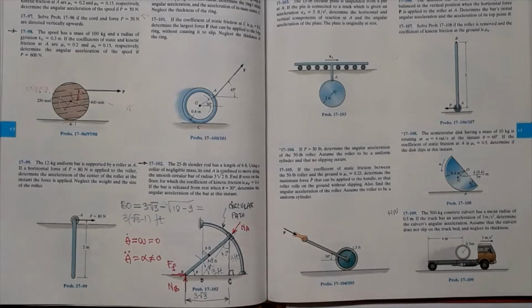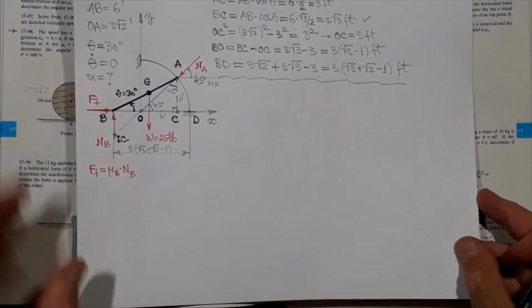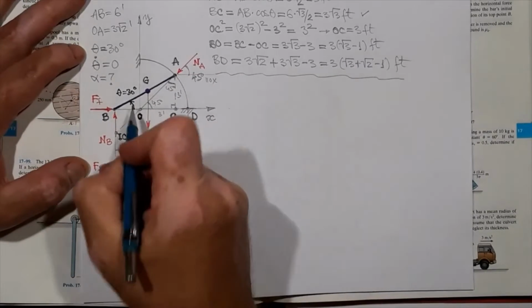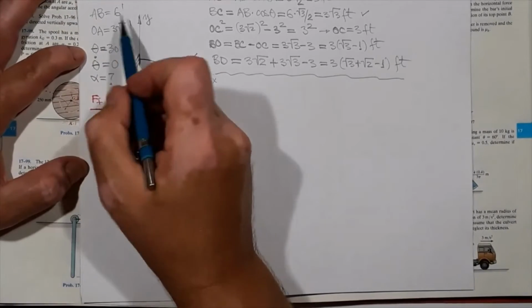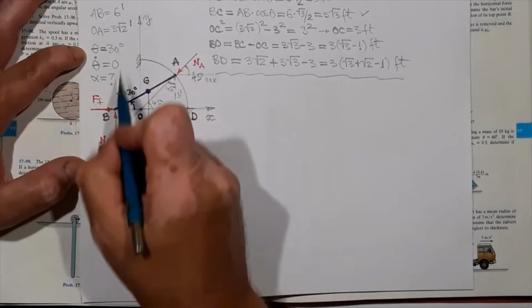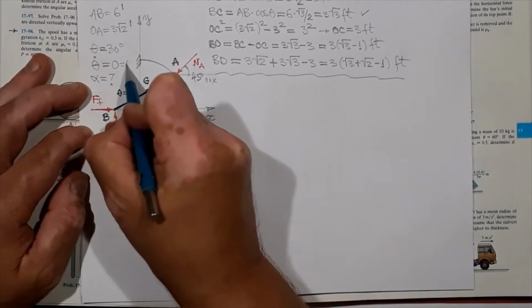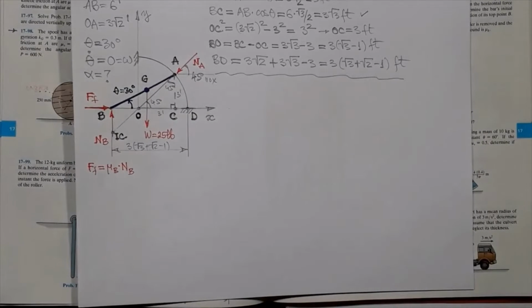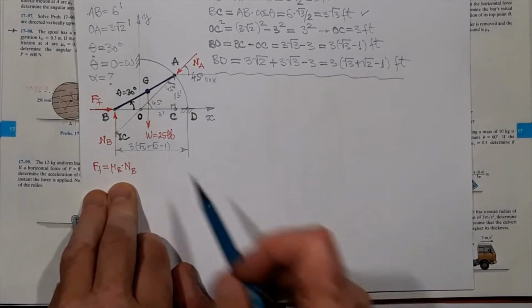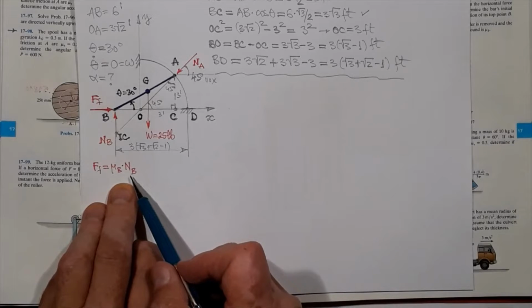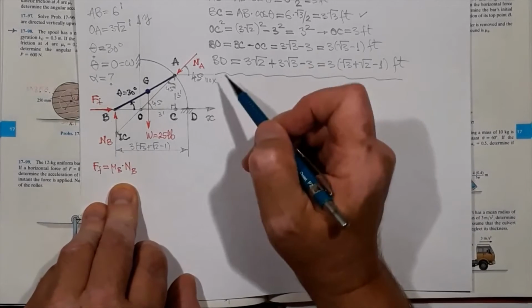of the bar. Okay, so I drew the figure here, trying to have it at scale. Summary of what's given, the lengths and the bar length and radius and angle, theta dot, which is omega at 0, alpha unknown. Friction force, since it's in motion, we have kinetic coefficient of friction, which is given as 0.4, times normal B, the normal force.